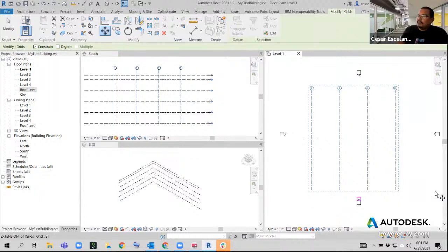And so across all the objects, you can see this dash line. Revit remembers this checkbox that is constrained. So I can only move this orthogonally, 0 degrees or 90 degrees. The next step is to pick a handle. A handle is a point in the space or a point on top of another element.